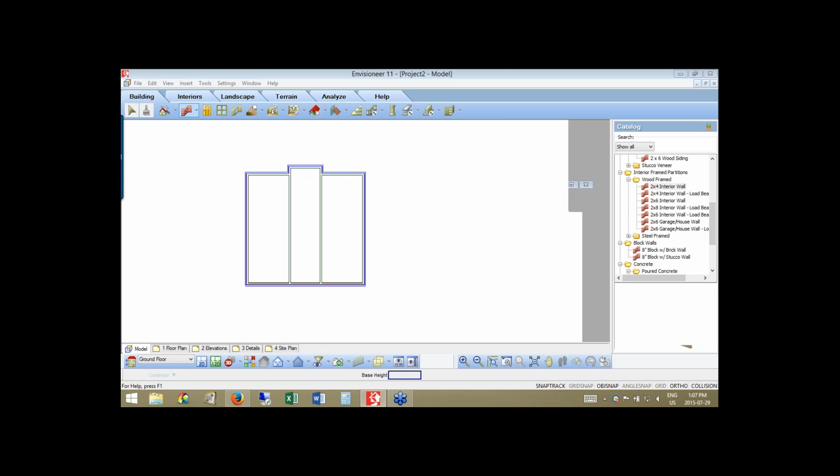And the next wall that I want to put in, I want it to be 16 feet away from that corner, that upper corner of that interior wall that I just put in. As you can see, as I move my cursor down, it's showing me just how far I am away from that corner. I have my precision set so that I'm working within the 16th of an inch. So trying to be very precise on pulling myself an exact distance away from a corner can be very difficult. So I want to make sure I take advantage of our offset tool.